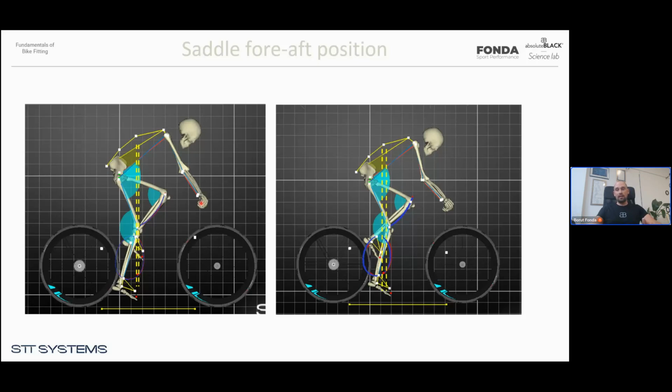Yes, there's also the angle of the arms, or the reach being too long, and so on. This is all very important. But when we speak about the distribution of the weight, knowing where the center of gravity is helps you a lot. And vice versa, when we speak about saddle problems and having, for example, too much pressure on the seat bones, one way is obviously to change the saddle and redistribute the pressure onto other contact points. But if the pressure mapping shows that the distribution of the pressure is correct and you just want to unload the saddle, in that case, you may be willing to move the center of gravity a bit forward to put more load onto the hands.